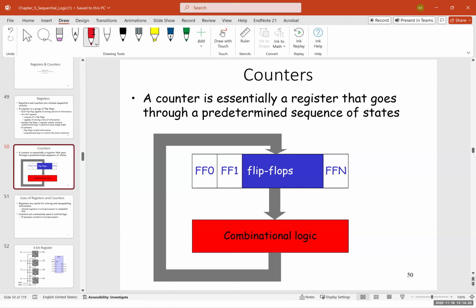Then we add 1 to it when we get 4. Then we save 4, we add 1 to it, we get to 5. If we don't have memory, each time we add, we go back to 0. So we're going to have 0, 1, 0, 1, 0, because we can't store that 1 to be able to add 1 to it to get 2, and so on. So the most basic part of any counter is going to be its memory, okay? If you don't have any memory, you don't have anything to add to on top of that.